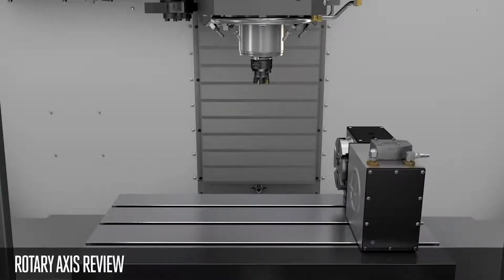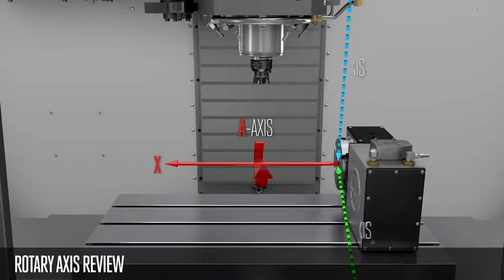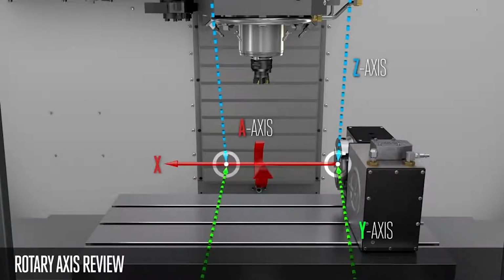The machine rotary zero point of each axis is defined by two coordinates. In this example, the A-axis rotates about X. The center line of the A-axis is defined by Y and Z-axis coordinates. So the A-axis MRZP can be anywhere along the A-axis center line. It can be here or here. The same concept is true for the B-axis center line and the C-axis center line.